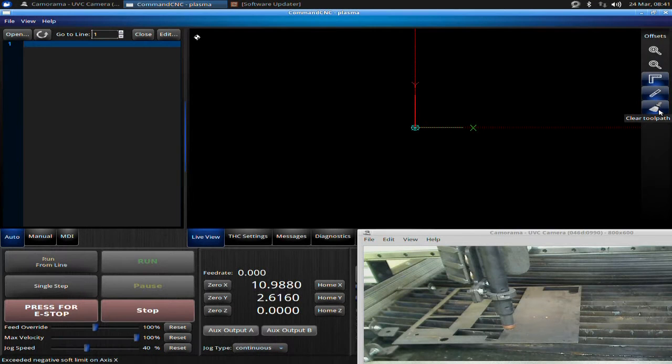Scott Cunningham, ArcLight Dynamics. This video we're going to be discussing manual data input and position recovery. So I got my machine powered up. I have set my machine 0. And what I want to talk about is typing in G-code manually to make the machine move to different positions. So to do that, you're going to click on the manual data input.